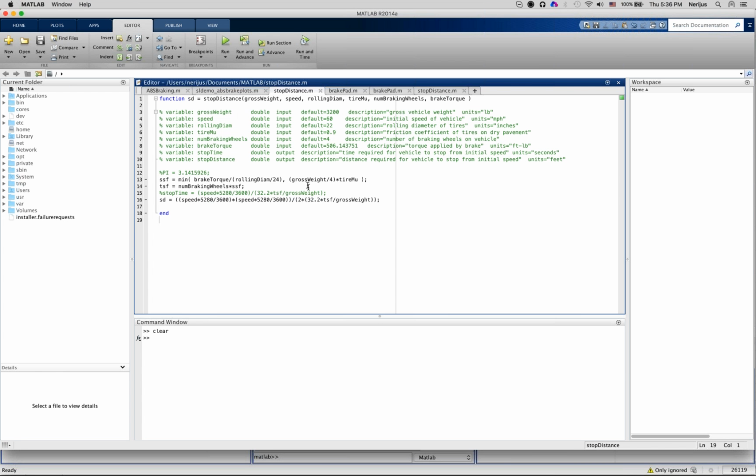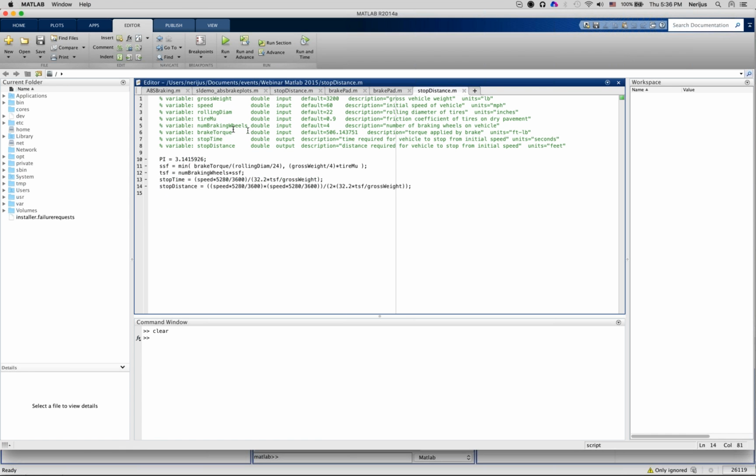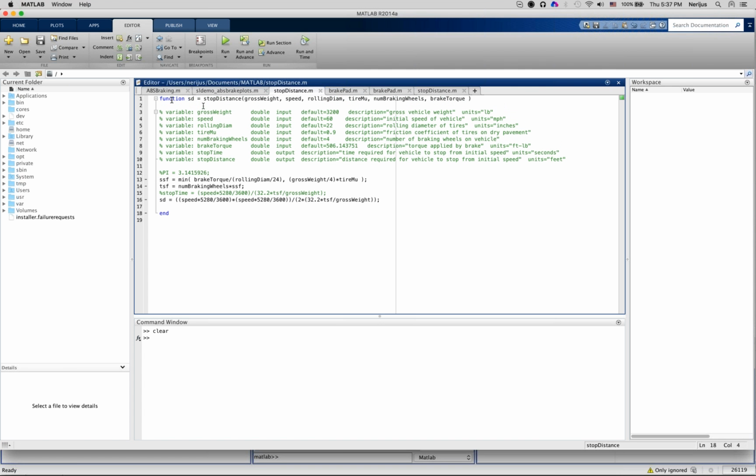So open this M file in MATLAB. Check if you actually have a function definition, which is not necessary but very useful, because if you have the same equations but without a function definition, we cannot identify what variables are used as inputs or outputs. But if you don't have it initially, just put in a function definition, name it, and list all those variables as parameters.